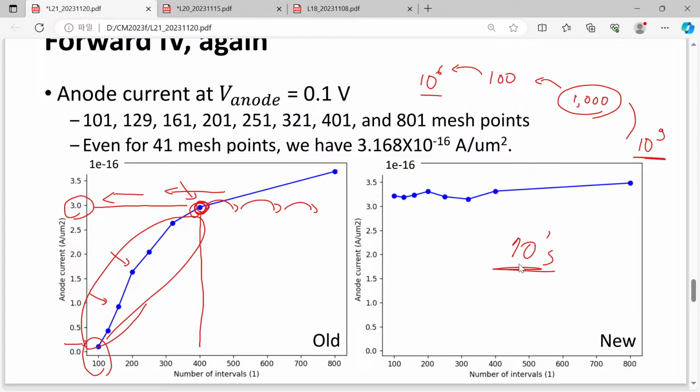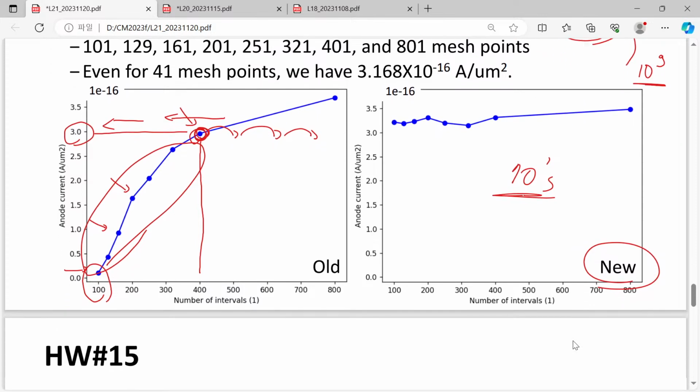So they eagerly needed a stabilized scheme to solve this continuity equation, and they succeeded in getting the Scharfetter-Gummel scheme. So I can certainly say that without the Scharfetter-Gummel scheme, we cannot simulate this electron continuity equation and hole continuity equation in a stable manner. It means that there is no field like device simulation. Okay, that is really important.